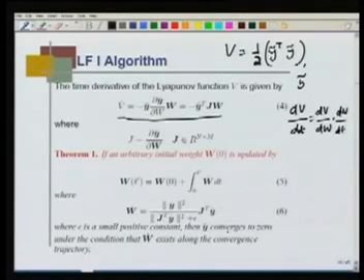Norm square means y tilde is a vector, so you take each element, square it, add them, and take the root of that, that is a norm. If you do not take a root, it is norm square. So, W dot is this norm square, again another is J transpose y tilde, another vector, again norm square, plus this epsilon, a small positive constant, and then J transpose y tilde.